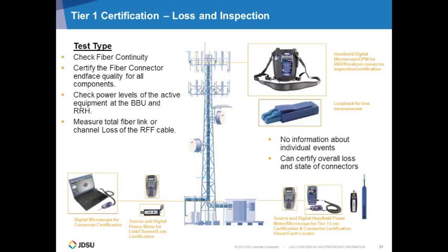That the correct fiber is plugged into the correct port. If you're doing insertion loss testing or OTDR testing, those lengths are the same, and it's going to be hard to verify that you are really on the fiber that you should be. So the visual fault locator, even though it's made to detect events, is used as the verification tool that I'm on the right fiber and I'm plugging in the right connector. Then the second thing, the biggest issue, end face inspection and quality of the end face.